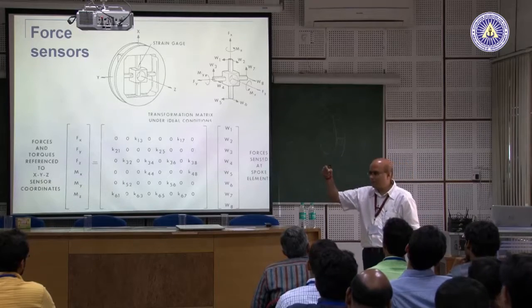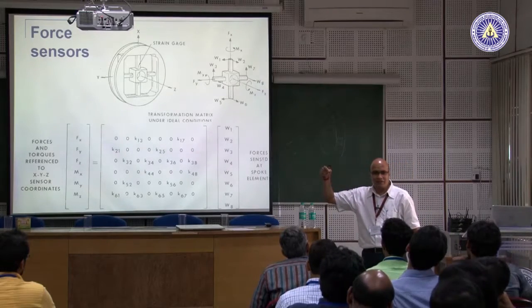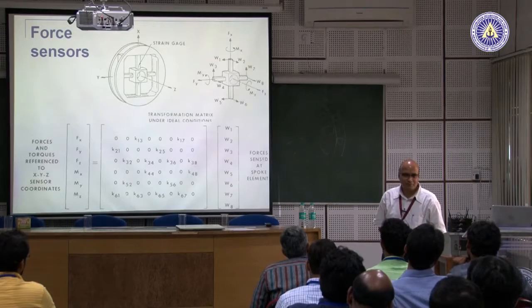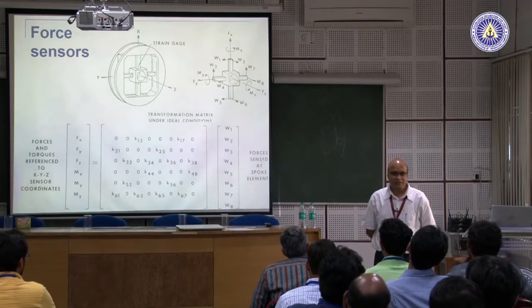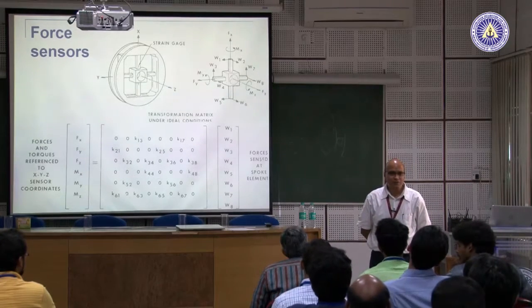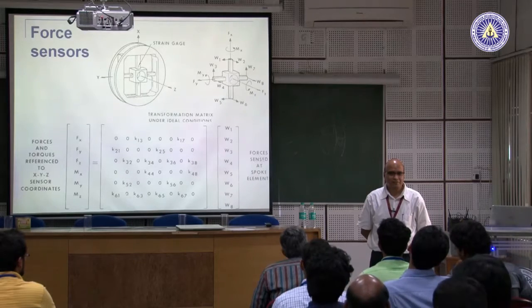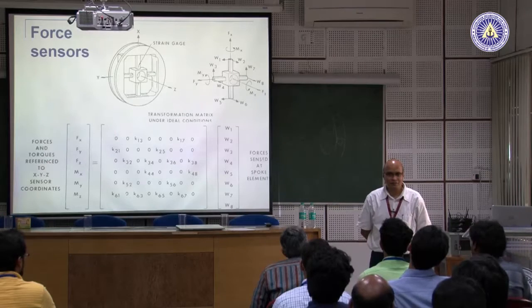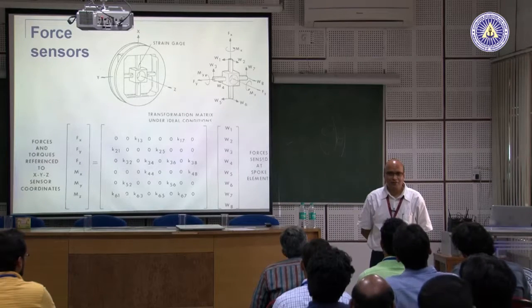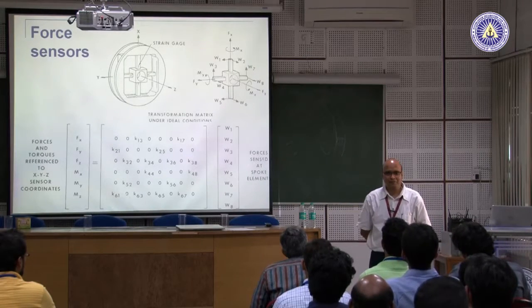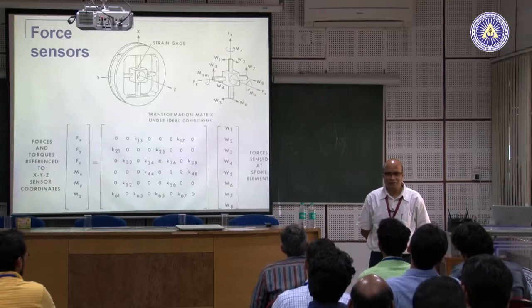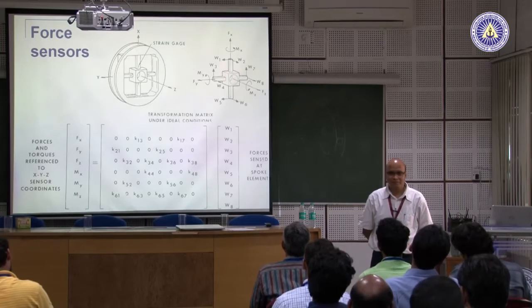So, at this point in space, if I say you please measure and tell me what is the force acting. So, can you measure force? You cannot measure force, okay, but you can measure the effect of force. So, you are measuring strain, you are not measuring force.